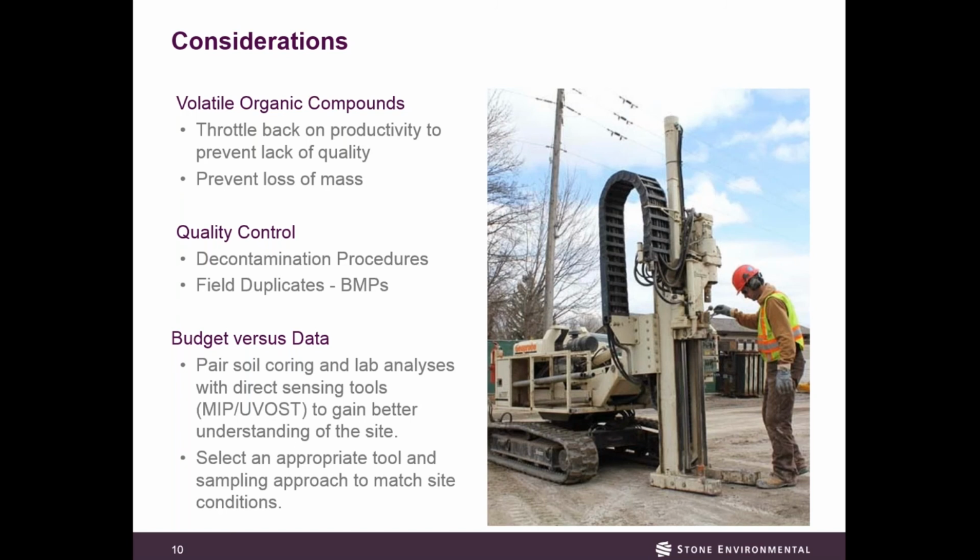So, decon procedures. Oftentimes I've seen drillers that just take out one acetate and put in another, put the cutting shoe back on, and put it right on the drill rig to be used again. There are components of the system that are touching the soil. If you're going through a hot zone and you have that cutting shoe or the inside of the core barrel, those things should be washed out. I mean, if they're showing up and they don't have any kind of method for decontamination, ding dang problem. You've got to be aware of that.